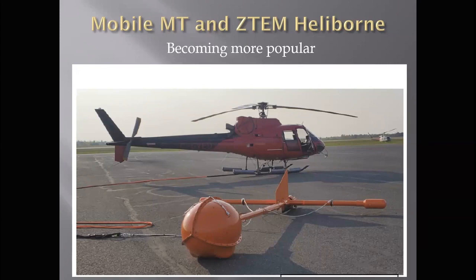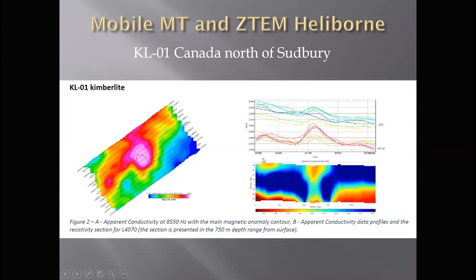You have something on the ground that measures the telluric current in the X direction, and something that measures in the Y direction. And then you use that base station on the ground, just like you do with a magnetometer or with a differential GPS, to modify what the aircraft is receiving. And therefore, you can map essentially deep conductors.